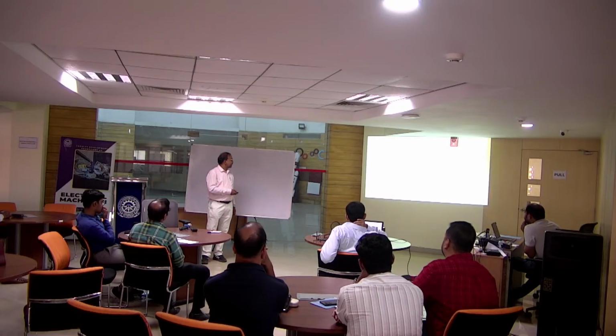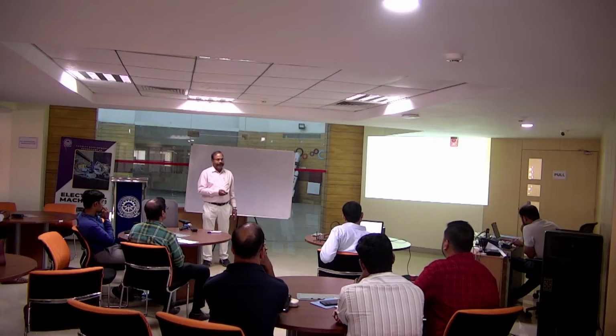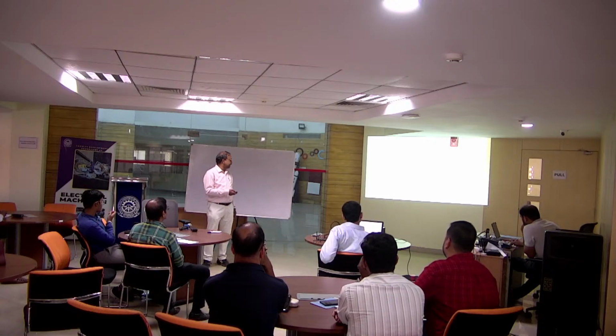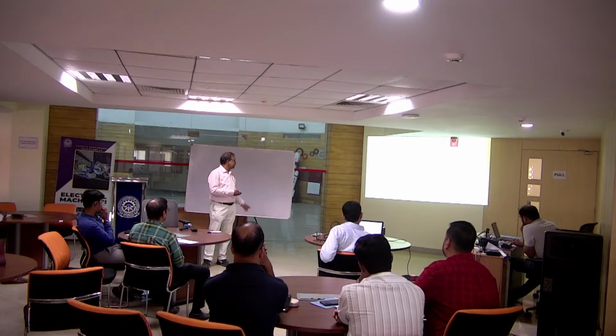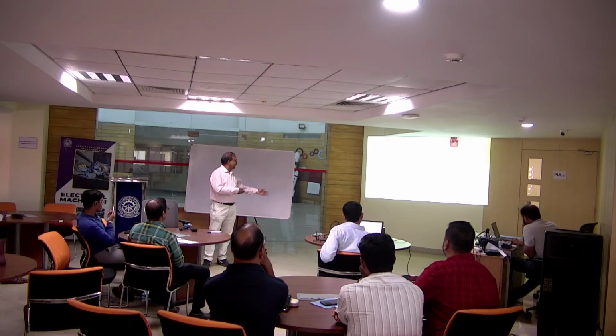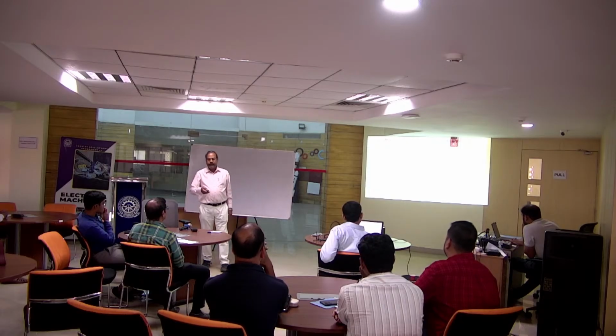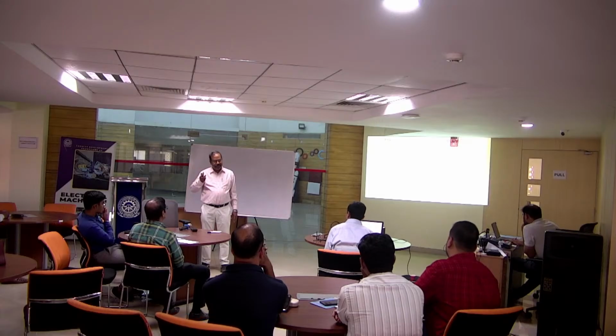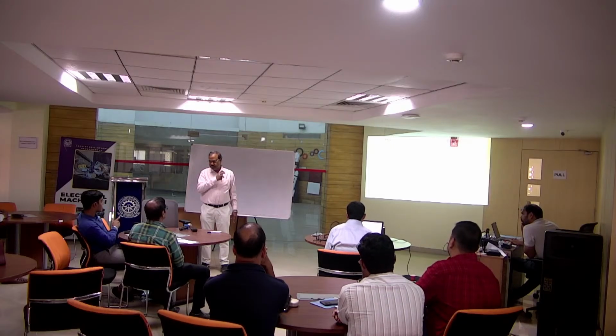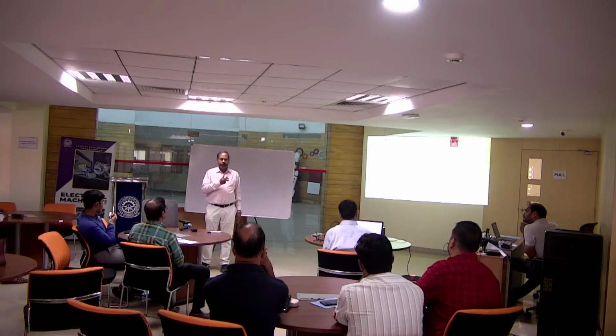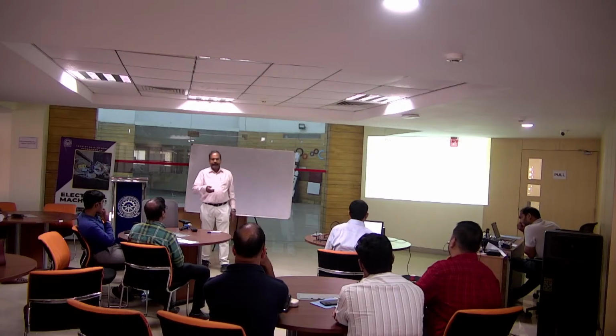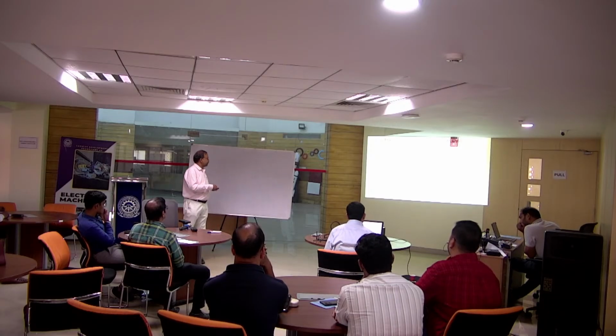Then dynamic braking has some variations, like DC dynamic braking, AC dynamic braking, capacitor braking, zero sequence braking. There are variations. Regenerative braking I have already explained. In regenerative braking, the machine is operated as a generator. You give power input to the shaft through a prime mover, and it operates as a generator and feeds power. So it is regenerative braking.